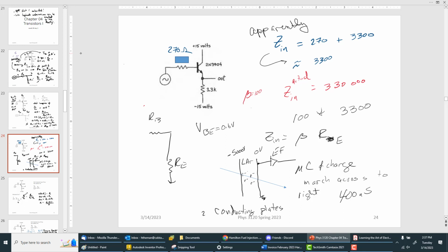And it's a special configuration that makes an input impedance of mega ohms, because you only have a few million electrons available there to drive a voltage, make say 1 volt. And if you try to drive a couple hundred ohms, it's never going to happen.